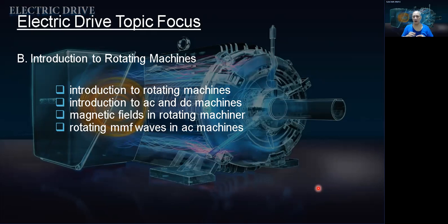it on, and at some stage when it is time to spin the clothes, it will spin. But you can see that your plug system is only one. So it must be only one supply, one phase supply. But how come it rotates? Either there are more than one phase, or probably there is some phase difference making that. Usually that's using a capacitor, but we'll talk about it later.